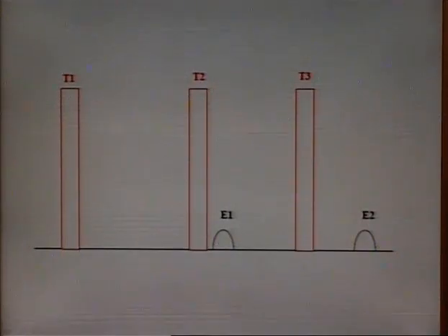This means there is a foggy situation around, where we do not know whether this signal is from T 1 or from T 2. Such an echo is called a second time around echo, because it has come after the transmission of the second pulse. Similarly, if a signal comes after transmission of 3 pulses, it is called a third time around echo, and so on.